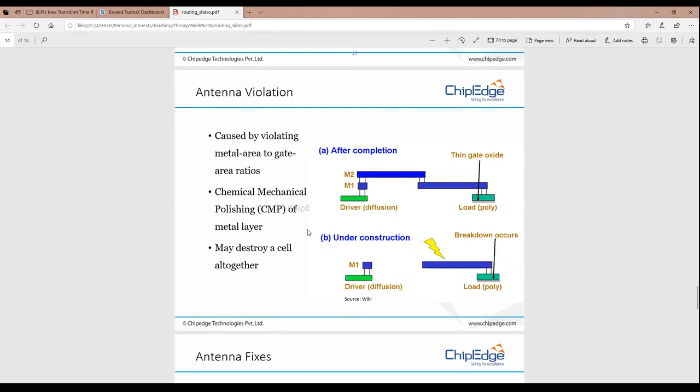And where does this charge come from, right? I think we discussed this in short. There are two metals that we are manufacturing, right? Aluminum or copper. Only the RDL layer, the topmost layer, is aluminum based, but the rest of them are copper. During the copper metallization or aluminum metallization process, at some processes, this charge accumulation, charge bombardment happens. For example, in aluminum manufacturing, the method used is called plasma etching or dry etching, right?